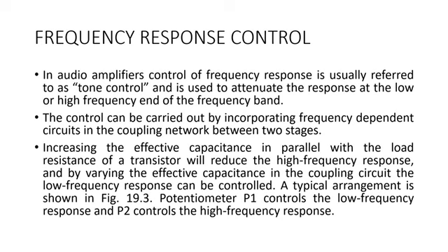What it means is that the frequency response plays a vital role, as it is used for controlling the tone. It may attenuate the low frequency, or it may attenuate the high frequency at the end of the frequency band. So the control can be carried out by incorporating frequency dependent circuits in the coupling network between two stages.